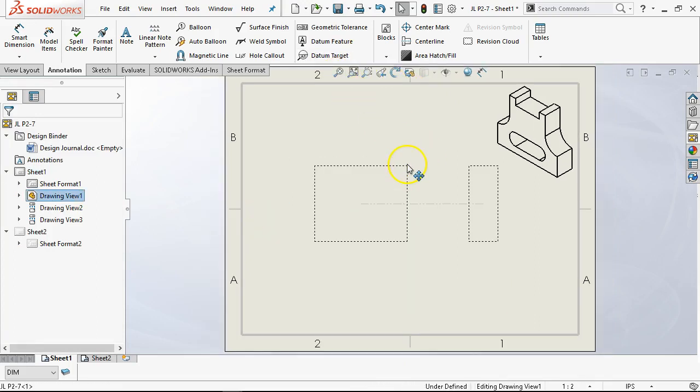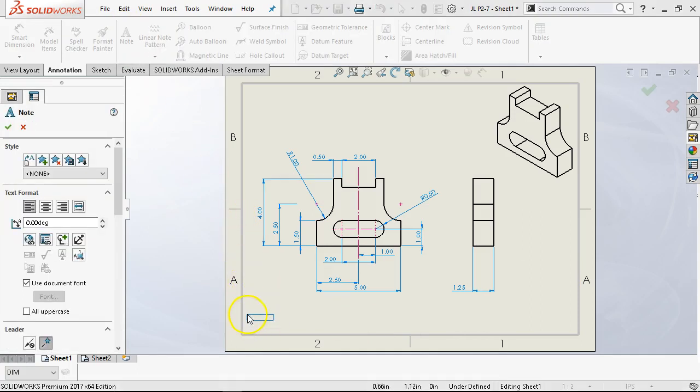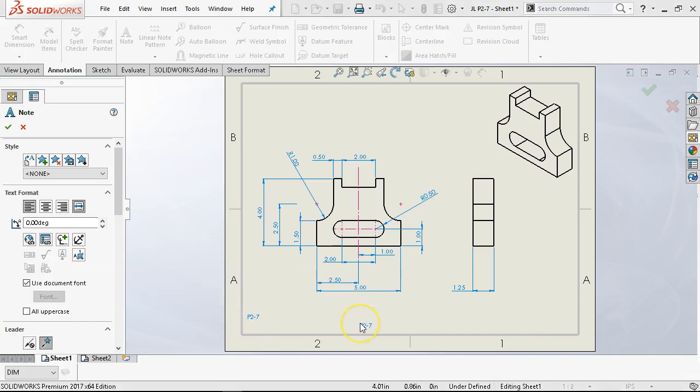All right. So probably the takeaway, the note, is that all of the annotations that would have come across the bottom, that would have traveled with the part and been associative to fill out the title block, are gone. I deleted them. I did not include them in this blank. So if I needed to put a note or I wanted to manually apply, and I don't know what I just hit, but that was interesting. And I could go through and start to apply those annotations.